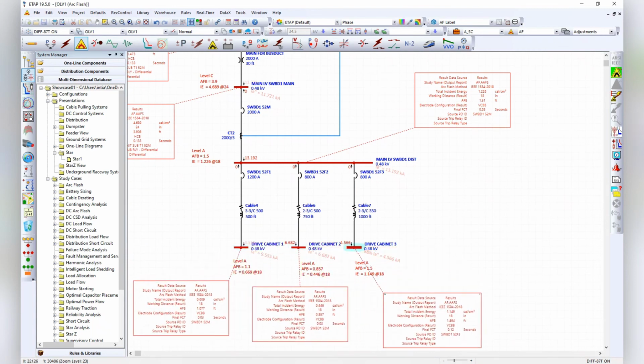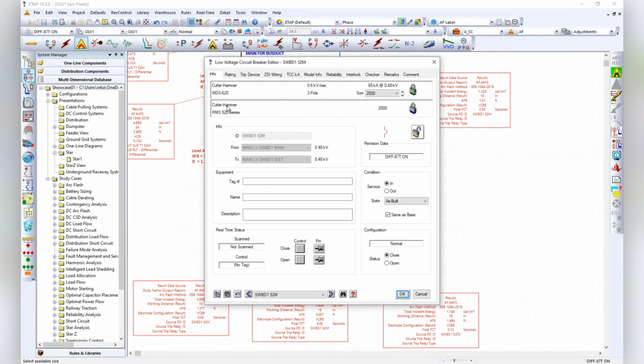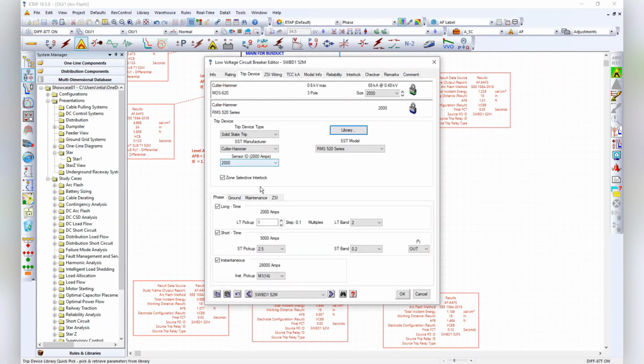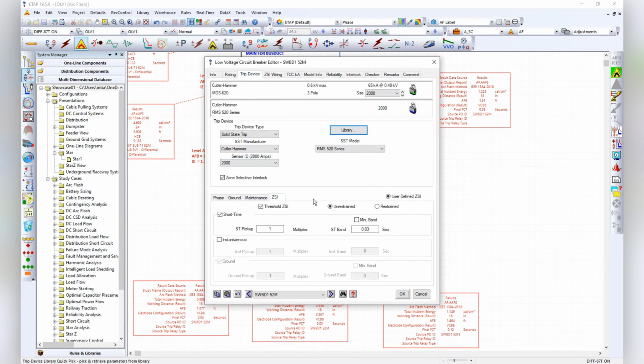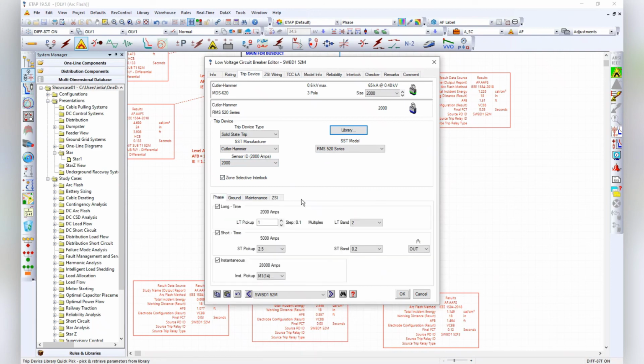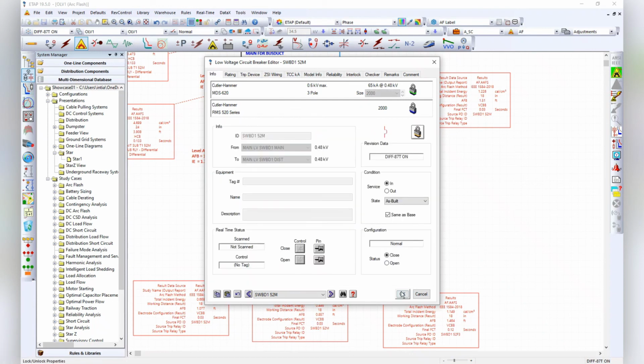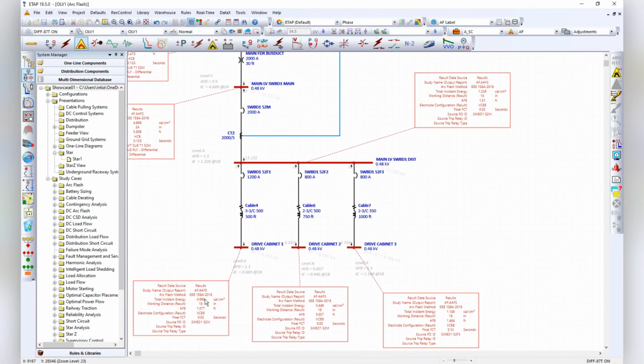And down here, it probably will be whatever it was on the main, down here by the main cabinets, and down here by the distribution is still gonna be driven by whatever I do on the main breaker, right? So in this case, I am pretty sure I left the main breaker on some selective interlocking. So downstream is doing whatever it was on selective interlocking. So the numbers will be the same downstream of the main breaker as if it was on the scenario under selective interlocking.